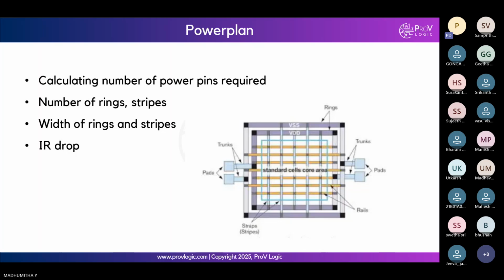That is why we use higher metal layers if we are seeing IR drop and electromigration issues. So, to answer your question, to fix these issues that we are seeing in the power plan, we will be using wider metal layers. Yes, ma'am. Understood. Thank you. Okay.